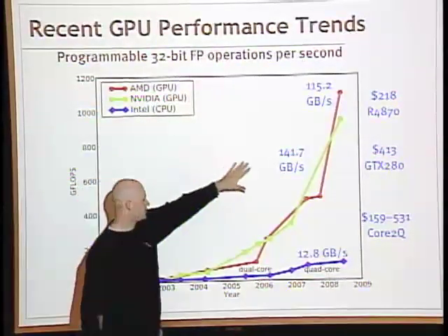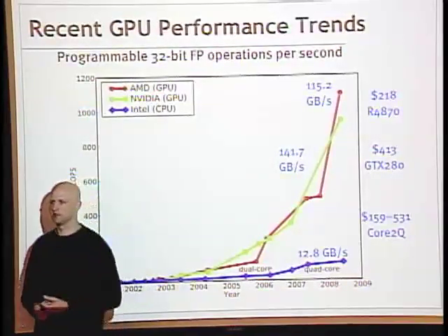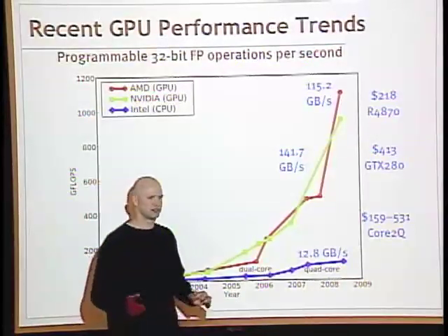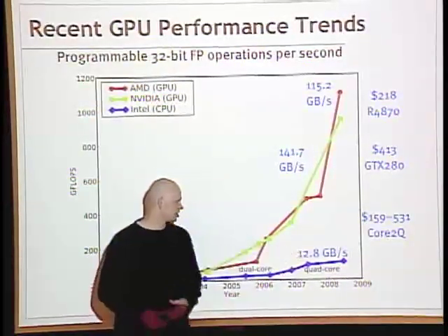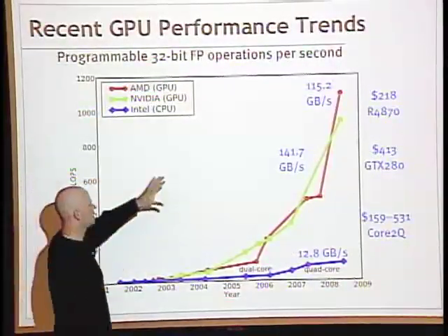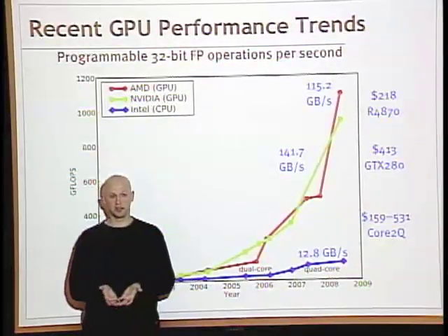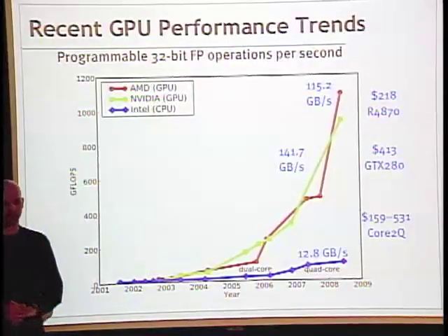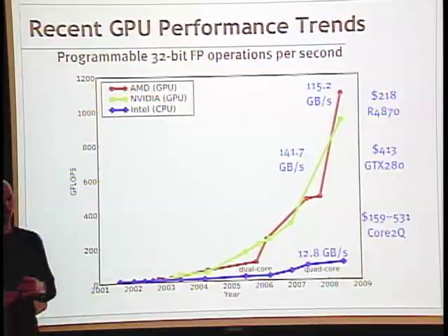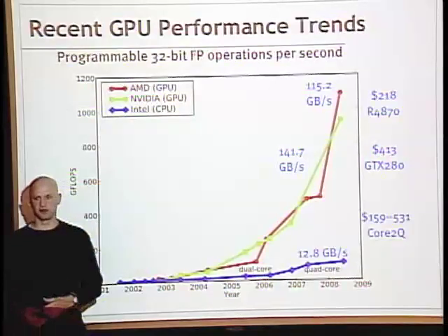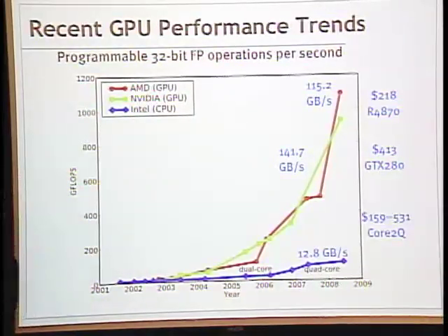The other figure that I have up here is bandwidth. So how much can you get out of the memory system? If you go buy a front side bus of, I don't know, whatever the fastest one is today, you can get 12 gigabytes a second from the memory into the CPU. But a GPU is very memory hungry, and they're willing to spend more money on memory hardware. They have wider buses and so on. And so you're also looking at having an order of magnitude more data bandwidth to play with. So for people that want to do high-performance computation, having 10 times as much performance and 10 times as much bandwidth is really a very welcome thing. So again, we'll be talking about why some of these things are in the course of this class.